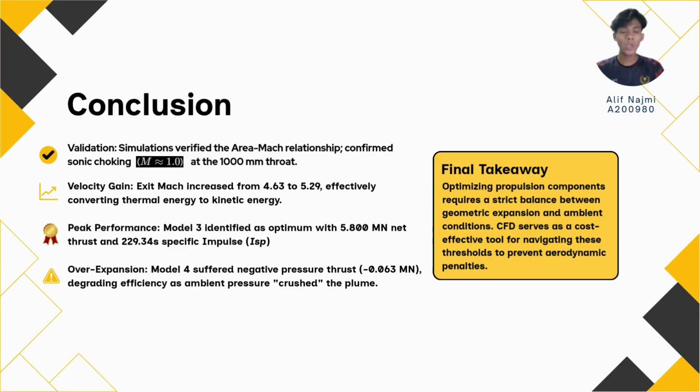In conclusion, our simulation successfully validated the area-Mach relationships, confirming the choked sonic conditions exactly at the nozzle throat. By expanding the exit diameter from Model 1 to Model 4, the exit gas accelerated from Mach 4.63 to Mach 5.29, effectively converting the thermal energy into kinetic thrust.